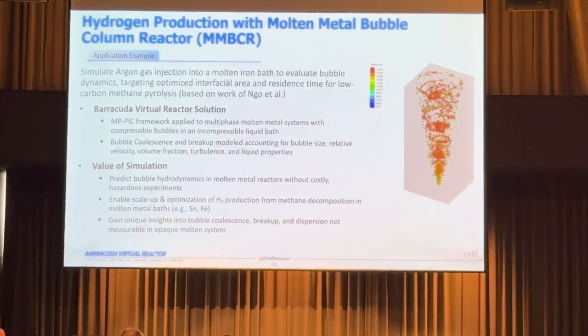The key fact is, this simulation doesn't have any reactions in it. But even without it, it's quite useful because, as I said, the bubbles as they move up are coming closer together and growing in size. Sometimes they're breaking off as well. And so, as you can imagine, because the reactions are happening at that interface, the hydrodynamics of how the bubbles move up is quite important if you want to understand the reactor behavior. And that's what I'm trying to do in this particular simulation here.